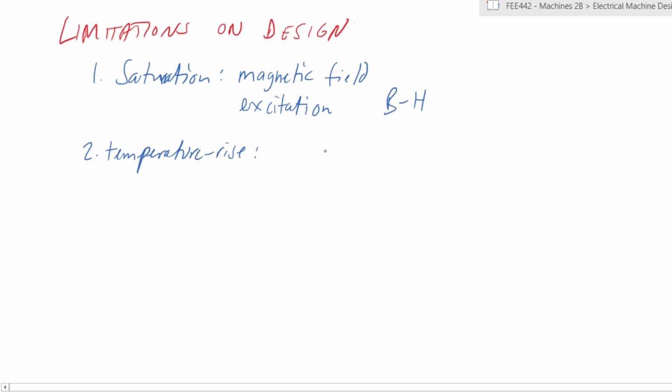Because these machines are generally machines that do work, there will always be heat losses, there will always be noise associated with that. And because of that, you must take into consideration methods of cooling. How will your machine be cooled? If it is working at the capacity that it is required to operate at, will you require special cooling? Will you require fans?